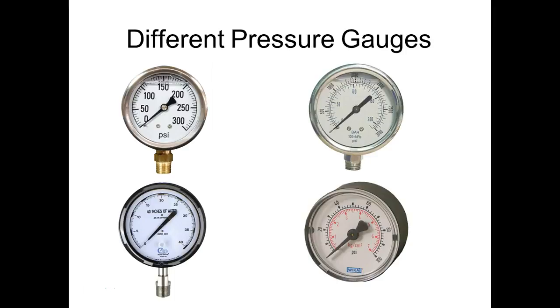If you could look, you could see the picture. I don't remember seeing a gauge anywhere other than maybe if there's an air pressure. Is there a gauge or something? That is the pressure gauge. There is a gauge, and it's a pressure gauge. Every service unit that has a pressure regulator on it has a pressure gauge. They have pressure sensors, but they don't have gauges. So sometimes we have pressure sensors that don't have a gauge on them.